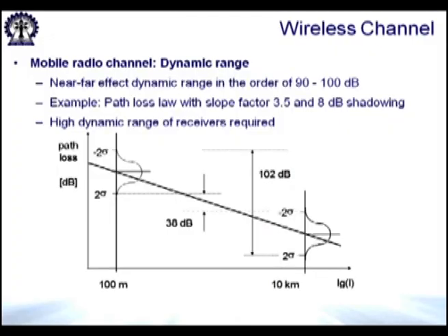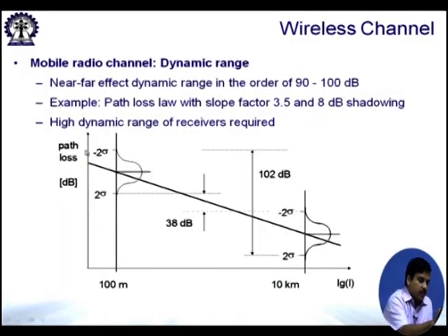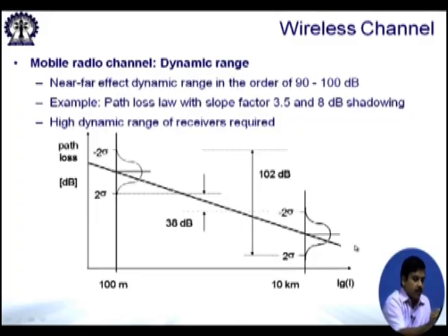If we look at typical propagation models, what we would find is, if there is path loss on the y axis and separation distance between the transmitter and receiver, there would be a certain slope which is found by the n_p or the area mean of received signal strength, and this follows the power law with a factor of, let us say, 3.5 in this particular example.